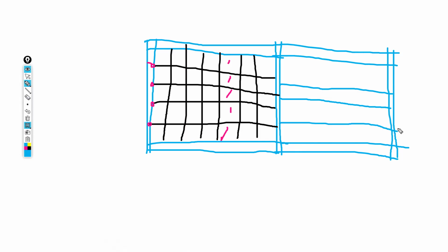For ribbed slabs, we provide FE strips. For it, we don't do meshing. This meshing applies only for solid slabs, where we shall have to do analytical strips, and then the analytical strips will take the results of this partition.